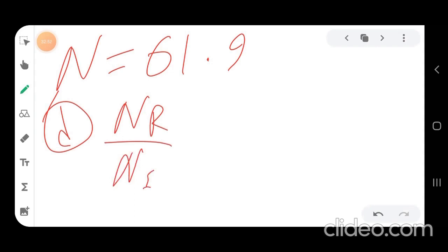Please note something I forgot to mention in the last video: if you are using a partial condenser, the condenser stage is included in the rectification section. And it is always a partial reboiler, so the reboiler stage is also included in the NS stripping stages. Okay, so we can use this correlation.